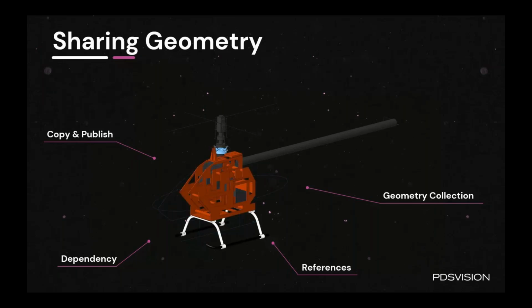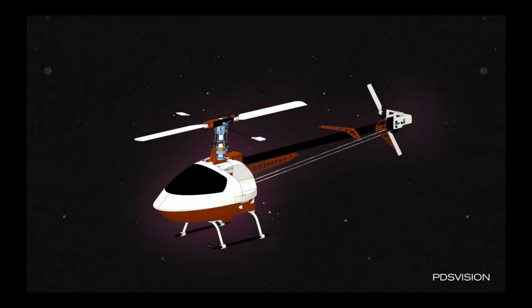So we share that information, and people in our teams go off and build the information off of that skeleton, so they can work on their own little area in context of the wider design. We've also got things like being able to control how that information updates when changes are made, but we'll go into that in a little bit more detail. So you've got all of these people working on different parts of the design, all working off that skeleton geometry. So these are a real key tool within the top-down design workflow.